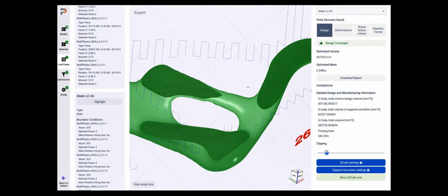Can users find the best part orientation? And Michael, I believe it's good for you to address this one. Yeah, that's a good question. As you change orientation, actually, this is a study that CTC Airbus have done, 11 load cases, and in some orientations, some load cases are critical. In other orientations, different load cases are critical.